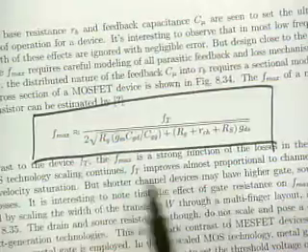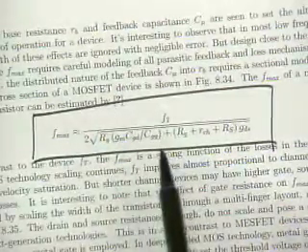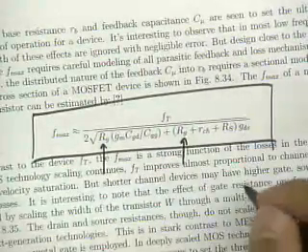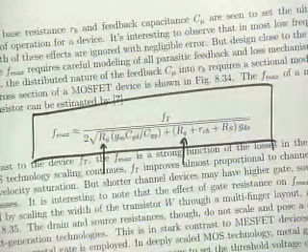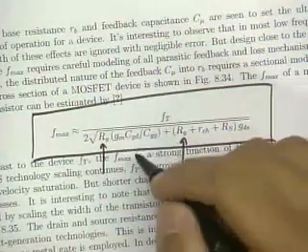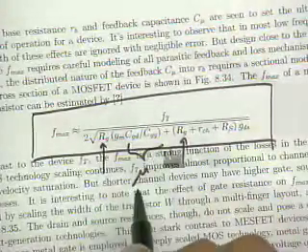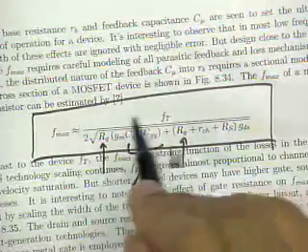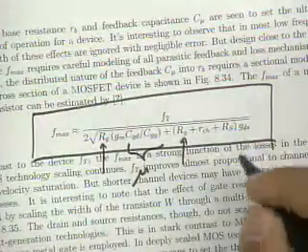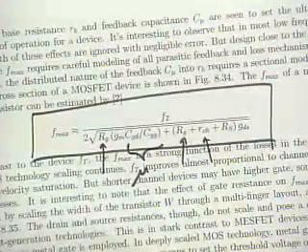And as a circuit designer, when we lay out our device, we can try to minimize some terms. We've already talked about how we can minimize RG, for instance. But at some point, we are stuck with certain process parameters. For instance, we called this mu early on, the ratio of C gate to drain to CGG. This is something that's getting worse and worse in a modern process. We also can control the channel resistance by putting more current in our device.